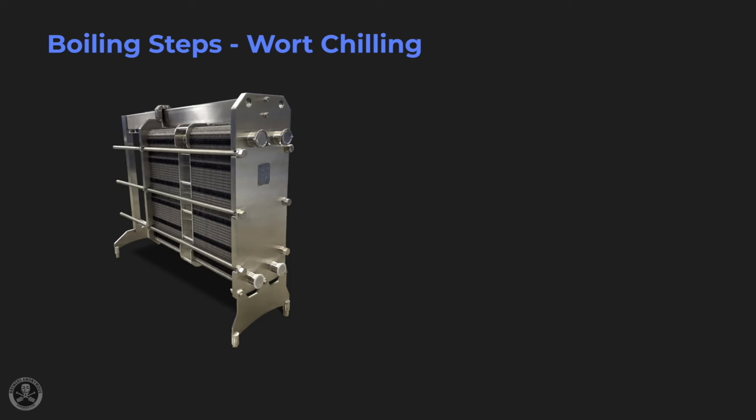This is done in most cases with a plate-based heat exchanger on the commercial side of brewing. We're looking at just one of the models of a chiller you might see in a brew house. There are some styles that are done in other types of specialized cooling vessels. You may see the term coolship come up as you're studying brewing. These are open-top, flattened, shallow tanks that spread the wort out and let the air cool it.